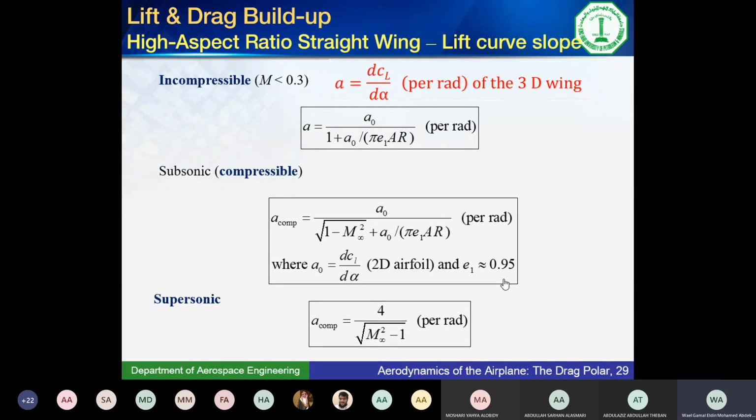The aspect ratio for a rectangular wing is exactly what you've said. It's the span over the chord. But that's only if it's rectangular. If it's not rectangular, like most wings, it's b squared over the area, the span squared over the planform area of the wing. b squared over S. The length, if you call it the length, which is the span of the wing squared, divided by the planform wing area, b squared over S.